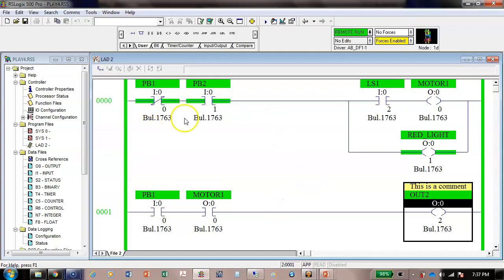But what's happening is this is actually showing my flow. So if I come up here and close switch 2, here comes switch 2, notice this guy right here closed. Now, these are the same ones, so it's telling me that this guy right here will never work, by the way, because when I change the position of this switch, this is going to open. So 2 will never come on.